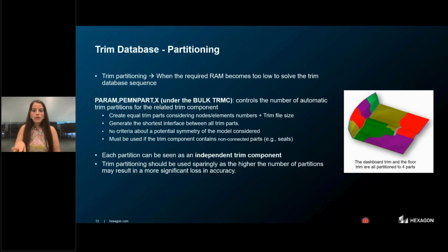Now, let's explore the concept of trim partitioning, which is very, very important for any MSC Nastran PEM analysis. This approach is specifically used in order to manage computational resources when we're working with large trim components in a simulation. Trim partitioning becomes necessary when the required RAM is insufficient to solve the trim database sequence. And we have this key control parameter over here, PARAM,PEM,PARTX, where X is the number of partitions that you are going to use,